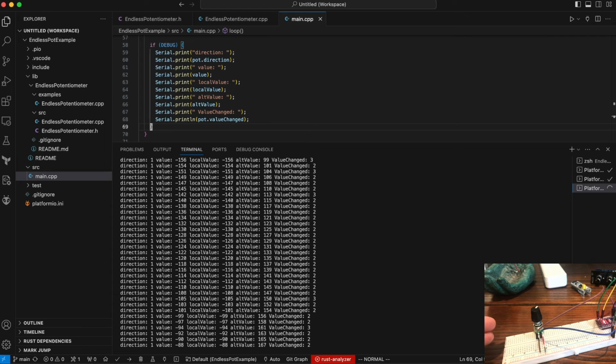Now with encoders, you're going to be dealing with bouncing, whenever that switch triggers from high to low. And so in order to compensate for that, you probably want to put some capacitors in there to smooth that. On the other hand, if you need something where you're going to be dealing with just digital data processing, then maybe an encoder makes more sense.